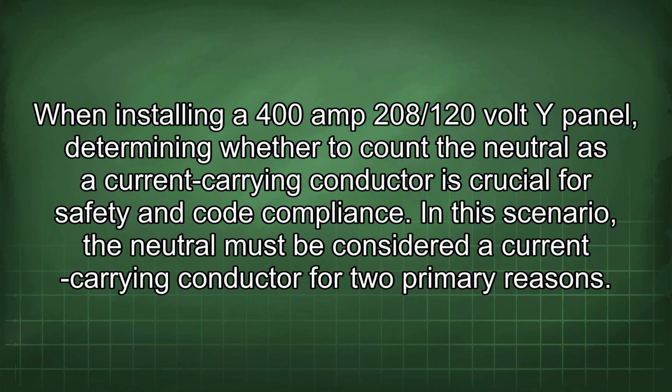When installing a 400 amp 208/120 volt Y panel, determining whether to count the neutral as a current carrying conductor is crucial for safety and code compliance. In this scenario, the neutral must be considered a current carrying conductor for two primary reasons.